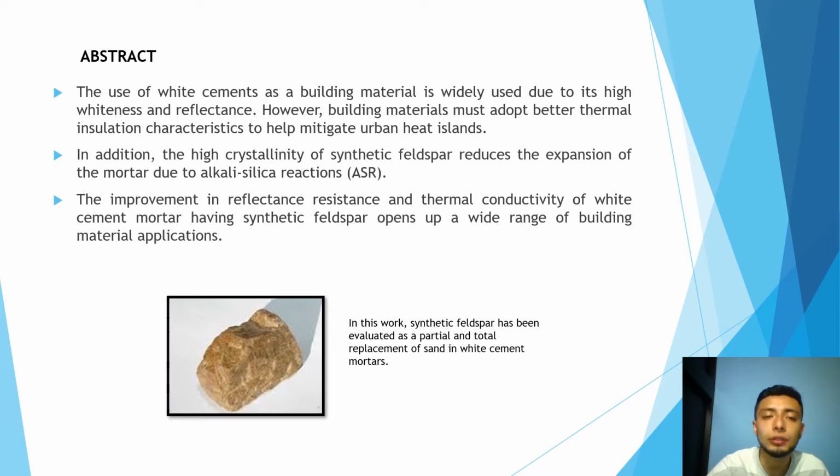In addition, the high crystallinity of the synthetic feldspar reduces the expansion of the mortar due to alkali-silica reactions. The improvement in reflectance and thermal conductivity of white cement mortar with synthetic feldspars opens up a wide range of building material applications. In this work, synthetic feldspar has been evaluated as a partial and total replacement of sand in cement mortar.